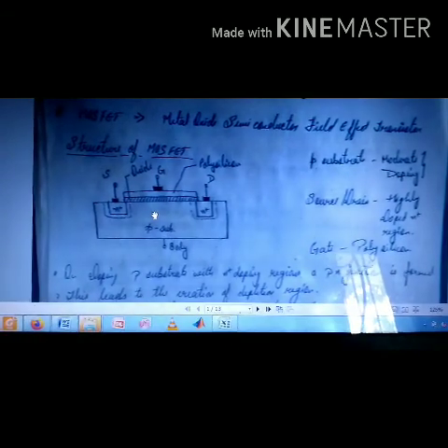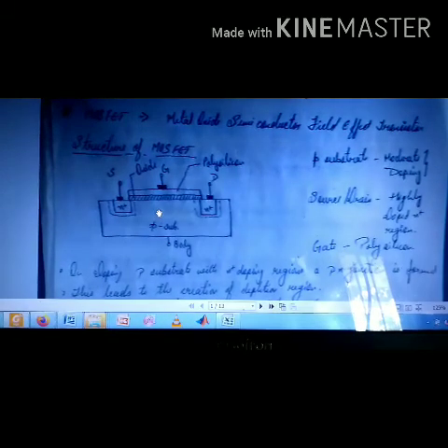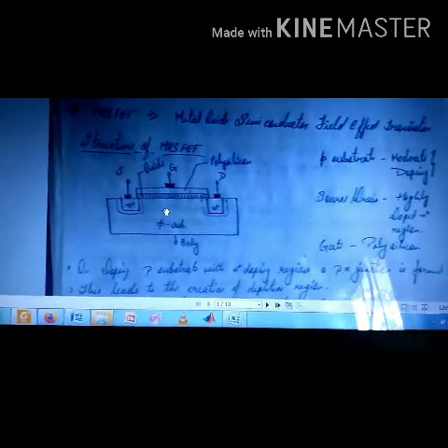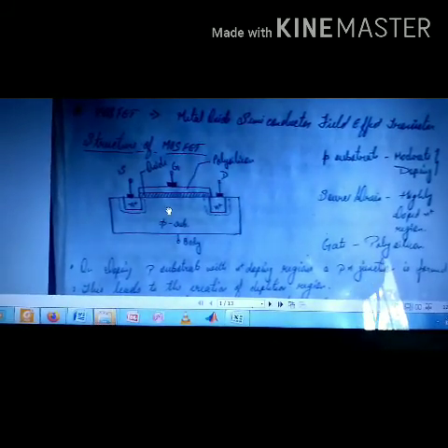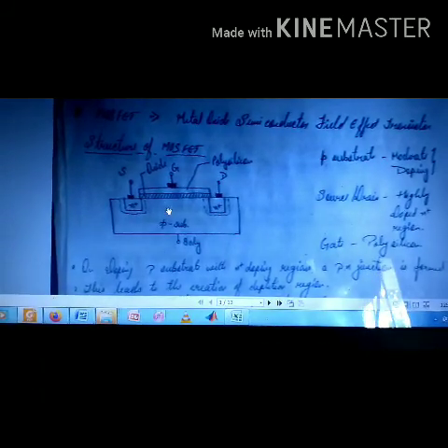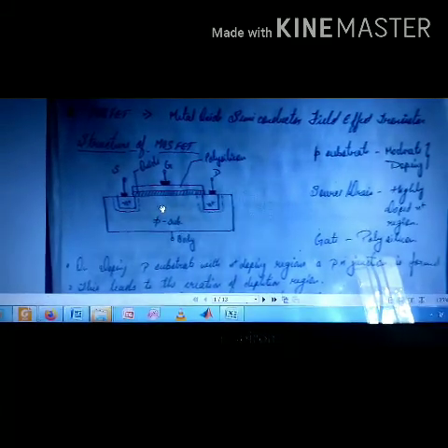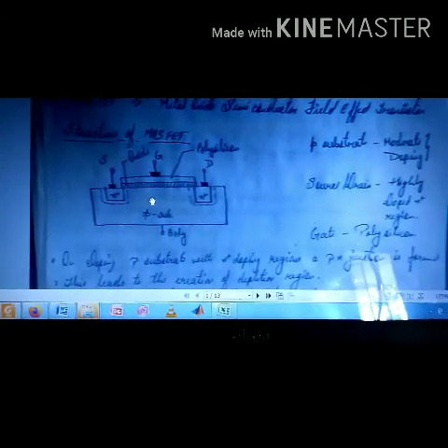Now, the oxide normally used here is silicon dioxide. Silicon dioxide and silicon materials are used specifically for VLSI application because silicon is first of all the most easily available material. Its properties are very good, though they are not as good as germanium, but its ready availability makes it a very good candidate. Its native oxide grows very easily, that's why this oxide layer will, in maximum cases, be of SiO2 material.